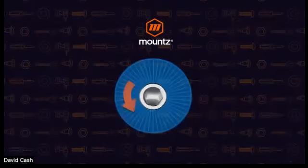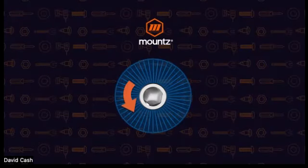Next is going to be the loosen test, or sometimes referred to as breakaway. We are simply loosening the fastener and measuring what that torque value is. Now, in this case, sometimes in the fastener there is some torsion that is built up, and you can actually see a lower torque value measurement because the torsion in the fastener is helping us when we're trying to move that fastener or break it away in the loosening direction. So that can play a part as well. Sometimes you will see that a fastener will take less torque to remove than it was to install it. And that's typically what is going on here.